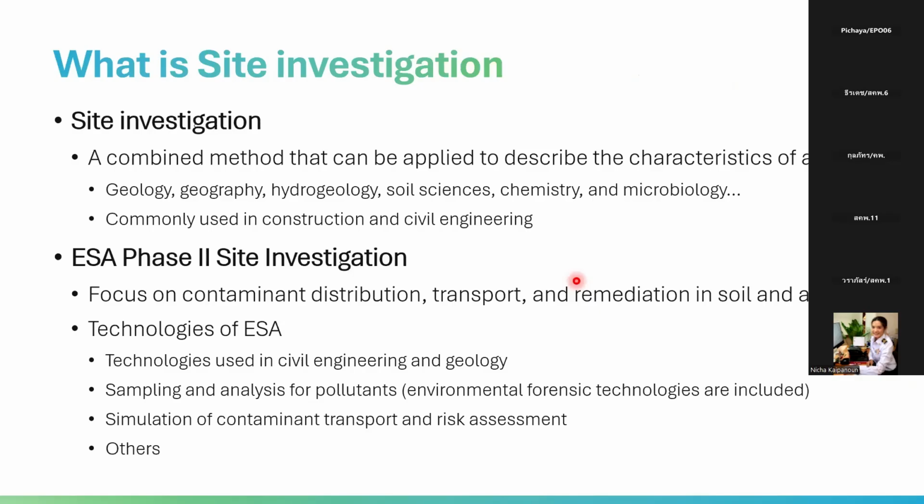It's a combined method that helps you describe the characteristics of a piece of land. The ESA Phase 2 site investigation has a relatively specific definition. It focuses on the contamination distribution and its transport, and the other purpose is to prepare for the remediation of soil and groundwater.